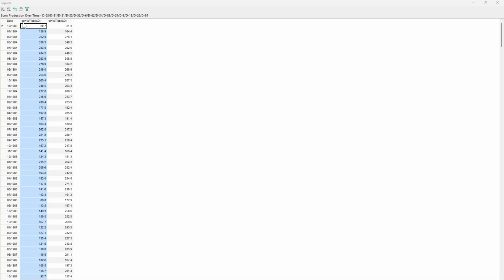So in this case, the reference is QO, which means rate of oil. The scenario is history, that is why we have an H here. The level is the well level. We are not checking the layer production. We are just seeing the production at the well level. And here the subphase, that in this case is total. So basically all this information is conveying that we are seeing the total well production of the history scenario and we are seeing oil, in this case liquid, but the initials, all the initials other than the O that represents oil in this case, are the same because it's also history, well, total.